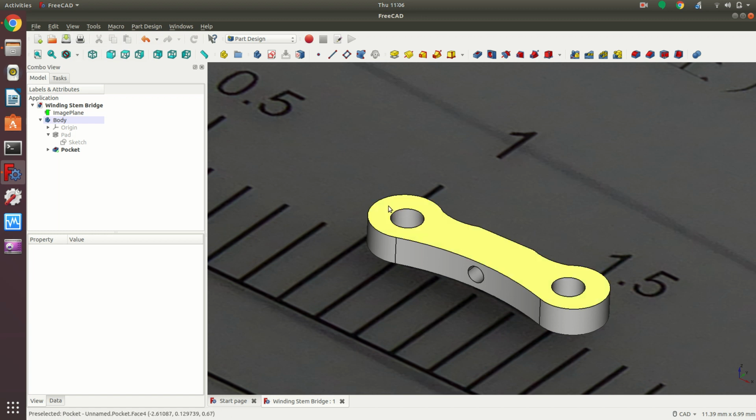If it were sunk in, we would do that in the drawing because then the end mill would do the sink. But as it is conical, we'll just do that with the burr at the end in the machine by hand, more or less. So we guide the machine by hand and that's it. Okay. Now we need a tool path to make this thing. And we got to think of what tool we need.